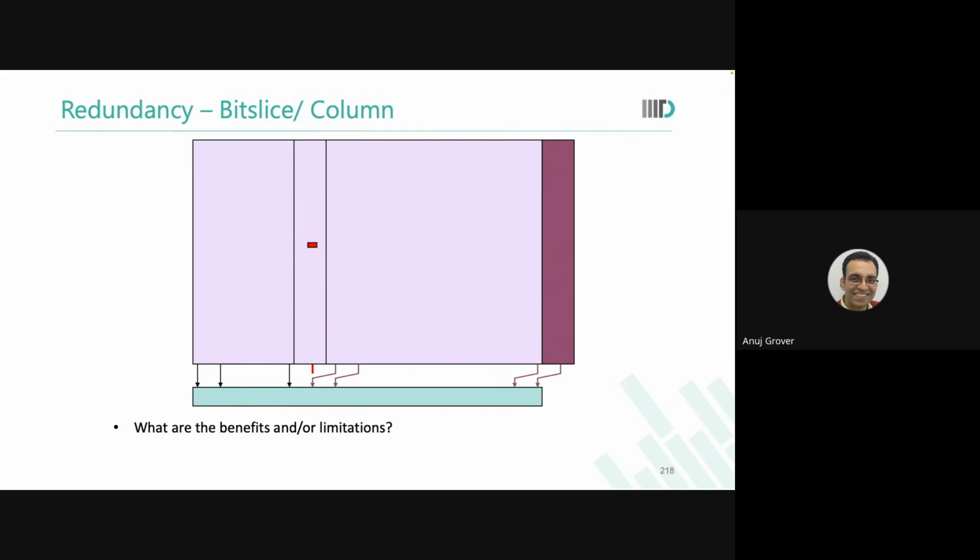On a chip, in the physical location, there are some places where the address pins will go, and there are some locations on your memory from where you will draw out the output. Now, because some particular column failed, can you change the place from where you will draw the output? Is the metal not physically connected there?